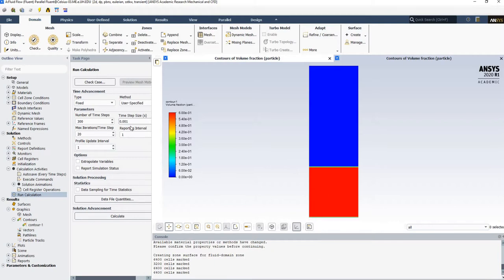Okay. Other way is if you go lower time step, Courant number would go low. So that's actually beneficial. But if you go to a lower time step, for example, if I say 0.0001, okay, that would take a longer amount of computational time to just do 3 second or 0.3 second simulation. So you don't want to go over there.